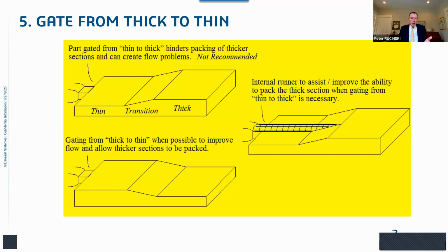The preferred solution, bottom left-hand corner: just gate from thick to thin, and you're going to be avoiding most of the potential problems that could occur.